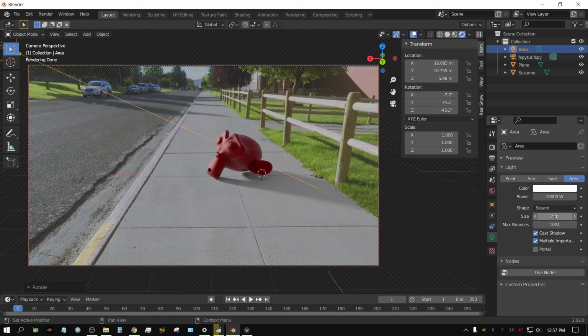It looks much better. The shadow is a little bit sharp in my opinion. If we was to, let's say, turn this up to 2, it looks a little bit better, maybe 4. All right. That's about right. Even the light that's cast on the monkey's face is the same as is on these poles.